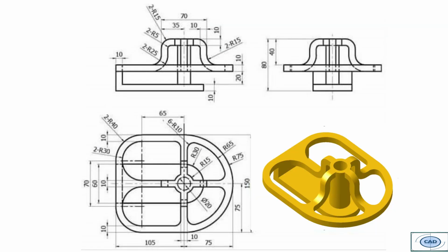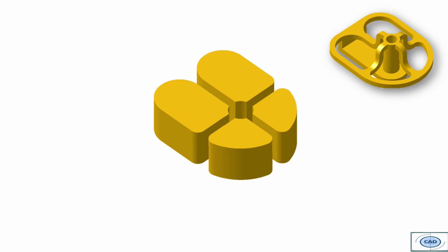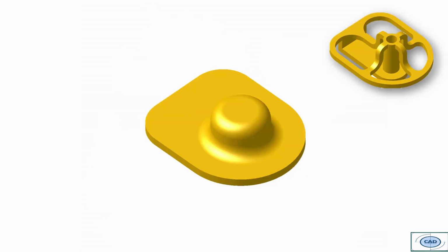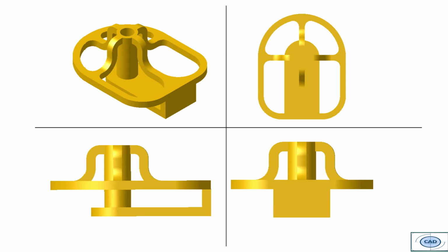So here is our today's task: to develop and create the 3D model like this. This is the first step of our tutorial number 4 task. First of all, we will create the geometry. After that, we will create a remove geometry to create that pocket. Then we will do the Boolean operations here. This is again the Boolean operation part. After that, we will draw this cylindrical part and this pocket. So this is the basic process to create this part. Once again, we will look at the first step, second, third, fourth, fifth, and finally we get a 3D model here.